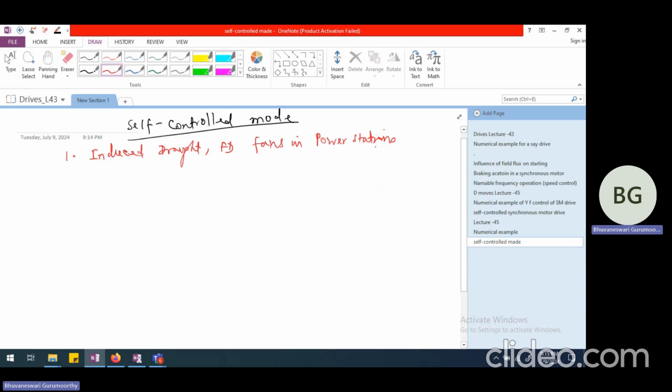Similarly, once the combustion happens, if the flue gases have to be pushed out through the chimney, then you have to force the flue gases out. That is done by a forced draft fan. These will be of a few megawatt ratings, and they should not have vibrations because of their large rating. Otherwise, it can create a lot of vibrations, which is not good for the structure at all.